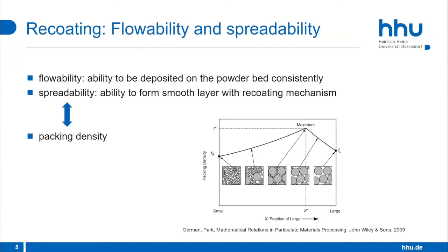So it's very difficult to strike the perfect balance between a good flowability and good spreadability and a high packing density. And this is something where the particle engineering comes much more into focus, which is also why I asked about the mechanofusion before, because we have very limited options from a pharmaceutical sense to optimize powders in a way as it is possible for commercial non-pharma materials.